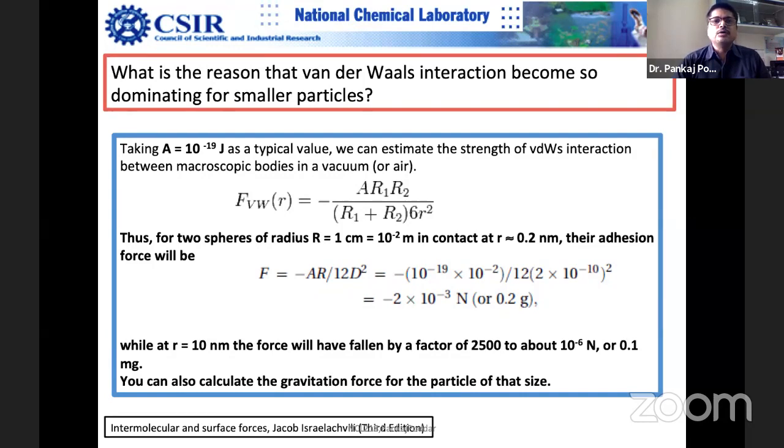You got it. Now, when you change the red laser to another wavelength, the surface smoothness has to match. You don't think this magic will work for a 1000 nanometer wavelength or 250 nanometer. Usually, these surfaces like the silicon wafer, which comes from a silicon fab lab, I have checked using AFM long back. I wanted to check that the smoothness is better than 2-3 nanometer. So you can see that it is definitely optically smooth.